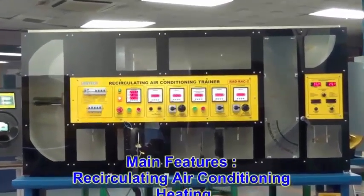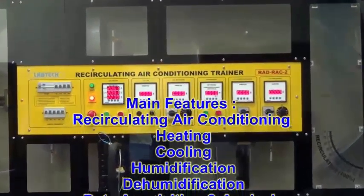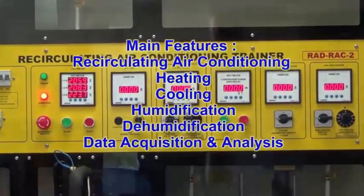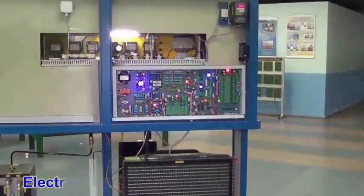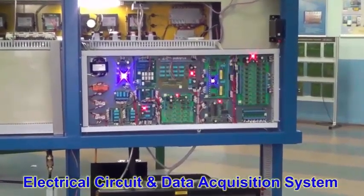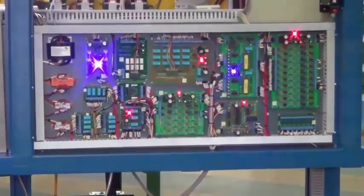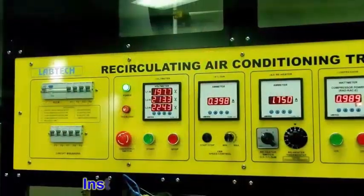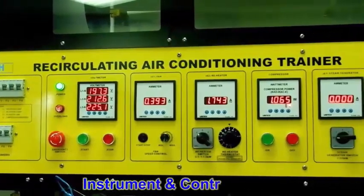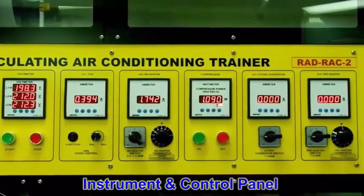This video shows Labtech's recirculating air conditioning trainer, which features recirculation and mixing of an airstream. The trainer provides for the study of a self-contained air conditioning and ventilation system that you would find within a typical commercial building. Airflow may be introduced from outside, recirculated, or mixed from within the system, thereby simulating open or closed loop systems. Students may simulate different air conditioning processes such as preheating, humidification, cooling, and reheating while logging data to plot and analyze air properties with a psychrometric chart.